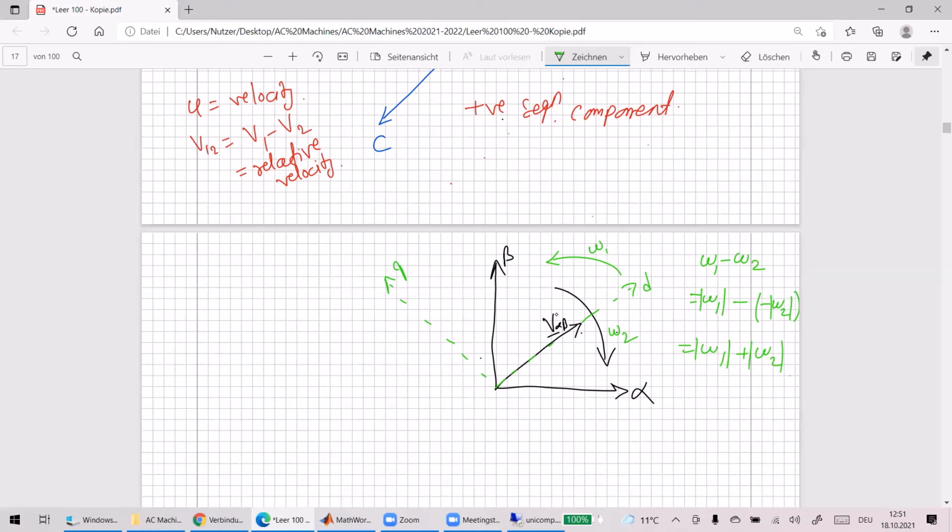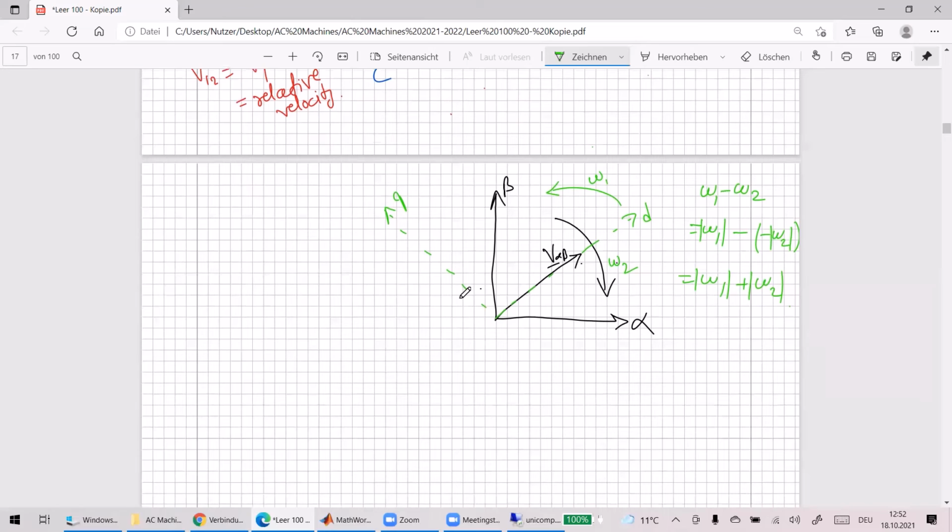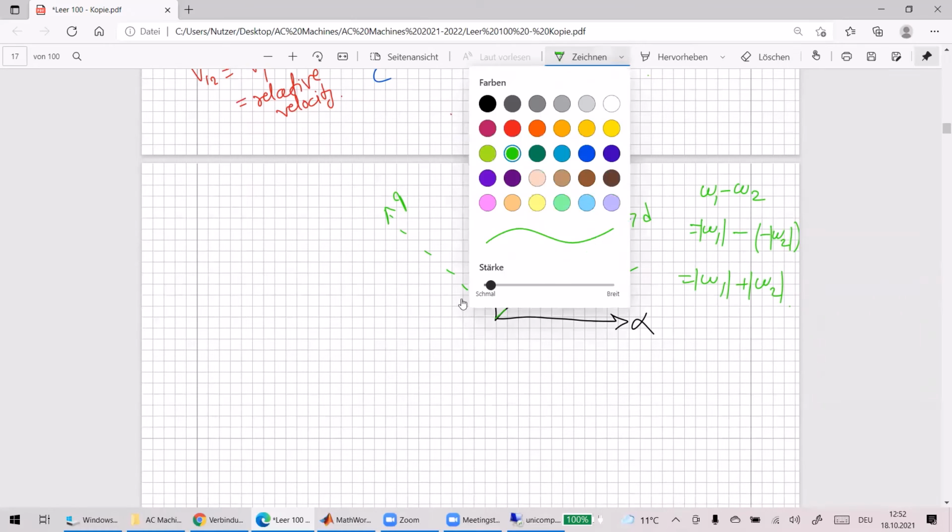So if there are both, let's say there is a positive sequence and a negative sequence, then which frequencies will you see in the DQ frame? For positive sequence, you will see DC. And for negative sequence, you will see AC, which is a 100 hertz component in this case. So let's find a general formula. Not for the fundamental component 50 hertz, but just a general formula. It will just take 5 minutes, then we'll go for a break. And then we can do lunch and continue again.